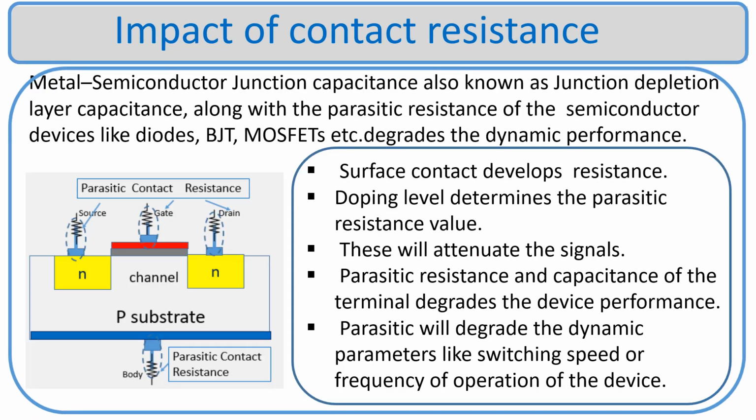Contact parasitic resistance impact issues are signal degradation, limiting of current transients, Joule heating, contact thermal expansion, mechanical pressure exerted on die, etc. The electromigration issues result in open contacts. All the above issues will lead to the degradation or the catastrophic failures that lead to reliability issues.